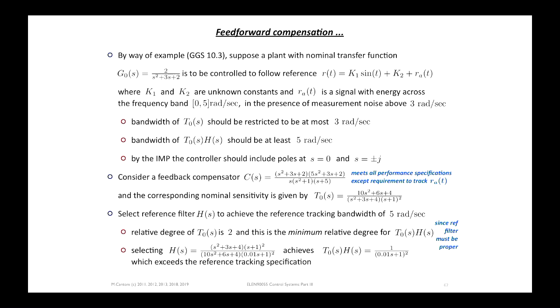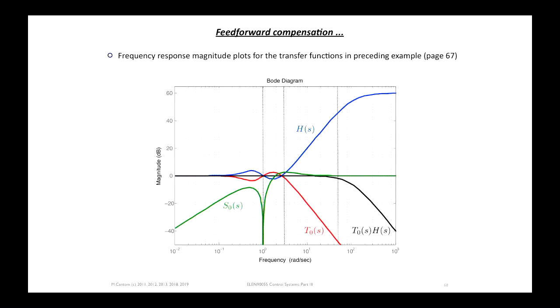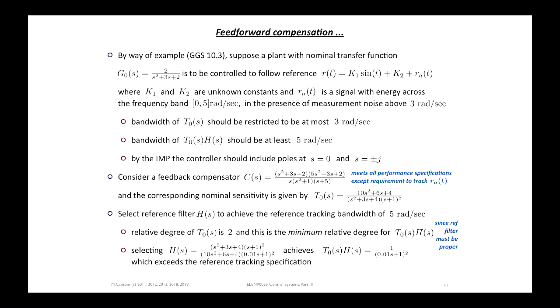So we're not going to be able to make it 1 everywhere, but we can choose to make it something that looks like this, so that it's flat over a very wide range of frequencies, and then we're controlling where it's rolling off here. And we're controlling where it's rolling off here by using these to cancel these, and then we're inserting that there. So we're using this to define what the product looks like in the end, and the rest of it is about cancelling these out, inverting them, in other words.